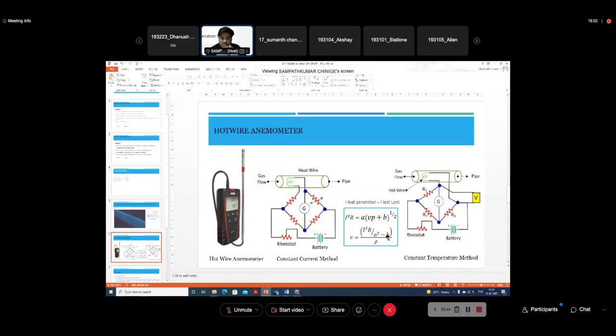Once you find out the standard velocity, you will use the hot wire anemometer, together at the same conditions, because the pipe line should be able to provide a proper or precise velocity of the flow. A controlled amount of flow should be flowing through the pipe. Okay, so you need to have a basic standard calibration setup to do this.